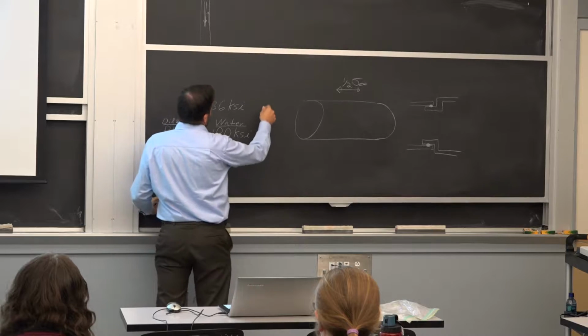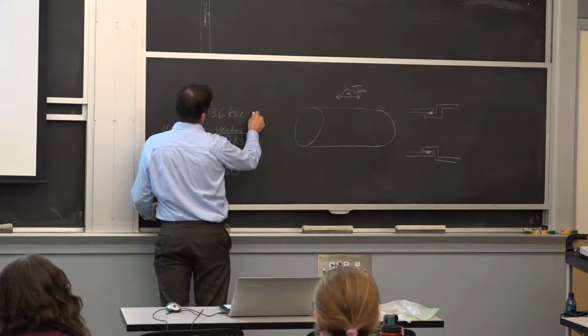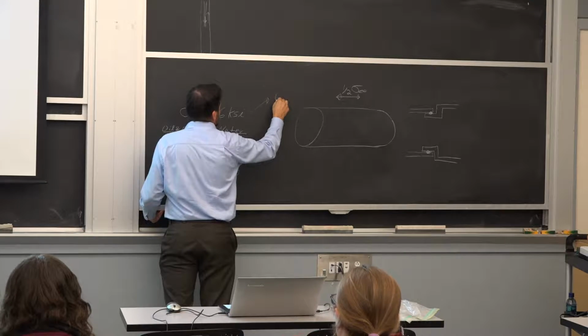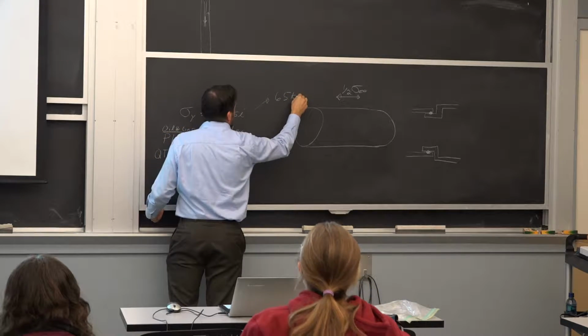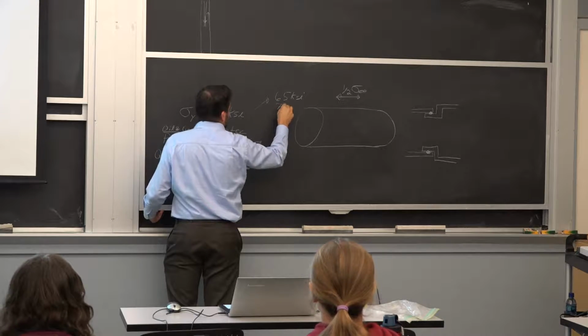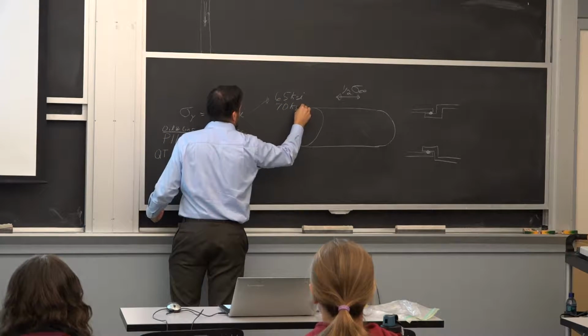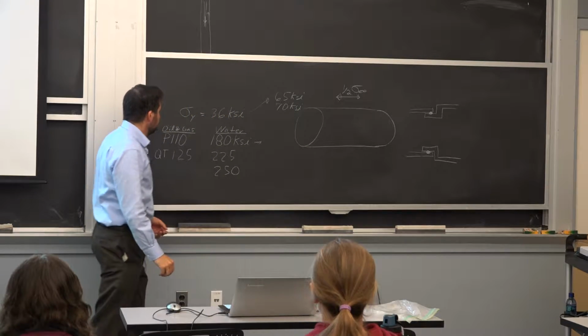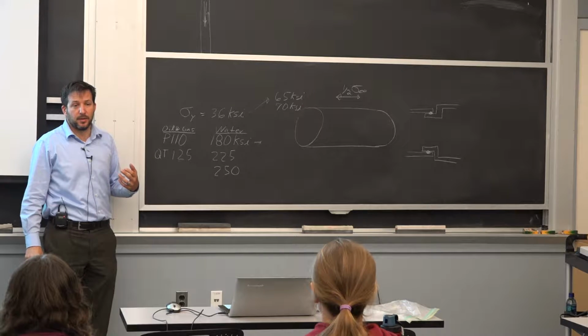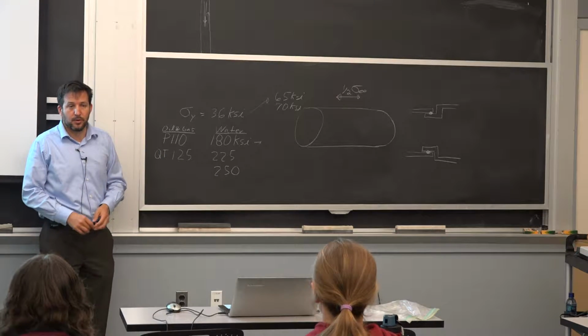Automotive, a lot of the steel is going to be pushed to the limit where you can still weld it. So 65 is pretty standard. You can get up to 70 KSI is typical, and you can still weld it. If you have components that you don't need welding for, then you go to the quench and tempered.